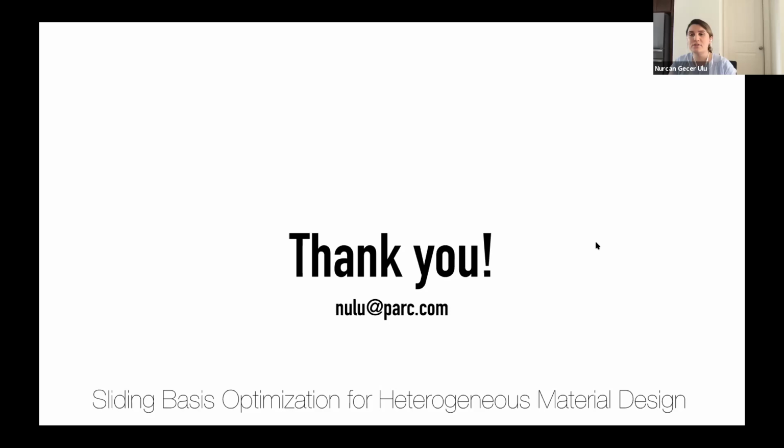For our approach, I used MATLAB's SQP optimizer with numerical gradients, and top88 incorporates the gradients and also uses the optimality criteria. So what I had was numerical gradients for 50 optimization variables, versus all 100,000 variables with the most optimized method using analytical gradients.